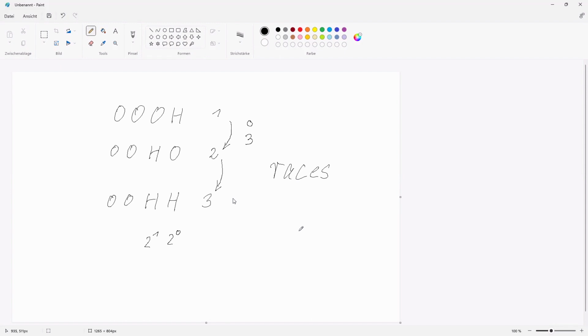Races, like a horse race also. The question is, who is faster than the other? And when you have races in the most significant bit, you jump between the switches in a wide range, in the half of the range. When you have a race in the most significant bit, it represents half of the total range, so that you get big jumps between the clear values. And that we have to avoid.